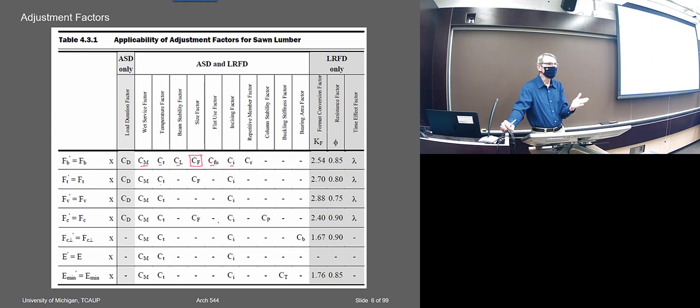Outdoor wooden bridges very often, I think the reason is because they use a denser lumber, a higher grade lumber, but they want to have it protected. So to get it to impregnate that denser lumber, they have to incise it. Anyway, but that's kind of rare too. Repetitive use, okay, for joists, yeah, that would be common.